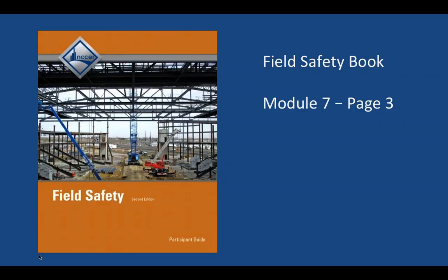You'll see that some of them are very similar. Also, in addition to that, another thing you want to keep in mind is look at the crane, look at the upper middle. We talked about dogging everything down, and there's the dog down sign, right? Just basically putting our hands over our abdomen in an X formation, and basically, what are we telling the operator? Hey, let's go ahead, dog everything down, right? Let's bring down the load. Let's go ahead and shut everything down until we can reassess.